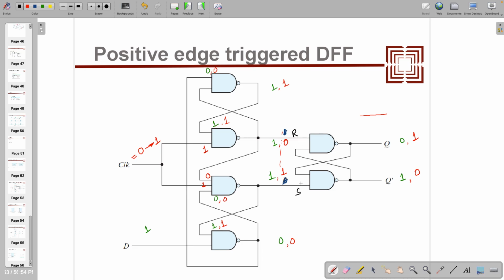This is actually the problem with the book. So I should call this one reset and this is set. So set equal to 1, because of that this becomes 1 and this becomes 0, right? So you can see going from 0 to 1 is actually taking this D as output, because this is what we were expecting. We are expecting that Q of t plus 1 equal to D when clock is moving from 0 to 1, right?